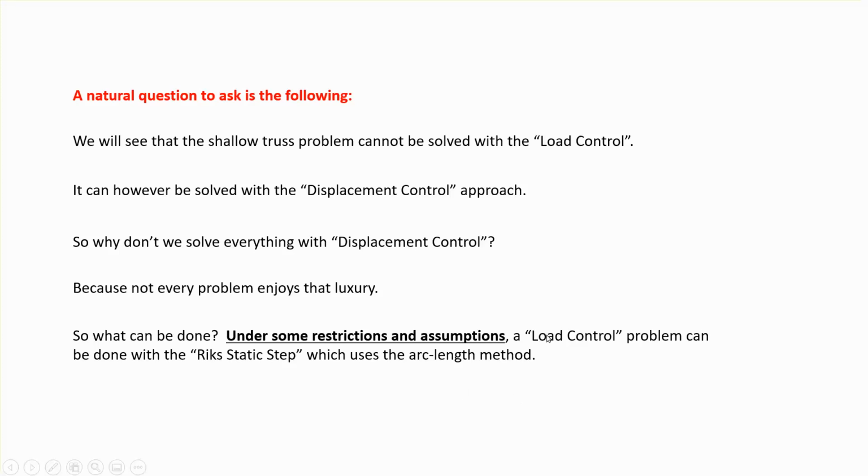So sometimes you cannot apply it as a displacement control problem, but you can do it as a load control because you know the load level, etc. You may not know the displacement level. Under certain assumptions, you can also do the load control. However, you have to use the Riks static step as opposed to general static step. I will do a video about this later on.